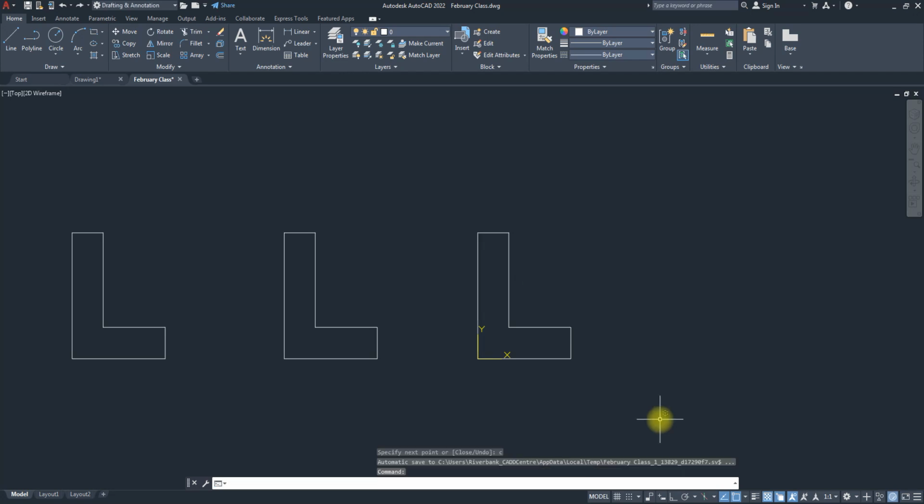But now, remember I turned off dynamic input. There's a way you can bypass all this at and less than using dynamic input. It's only for this purpose, for your polar, absolute and relative polar. If I turn on my dynamic input, let me first get rid of this, escape.